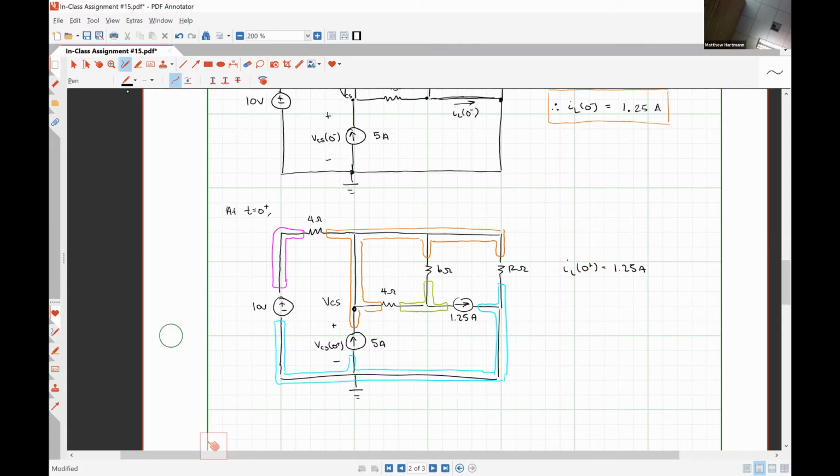We're trying to figure out what the nodal voltage at our orange node is, which I've labeled VCS because it's the voltage drop over the current source. Let's just call this guy simply VB for simplicity's sake. That is an unknown voltage. And down at the very bottom, in blue, we have that large reference node, which we say has a potential of 0. So we're going to have to do KCL at node VCS and KCL at node B.